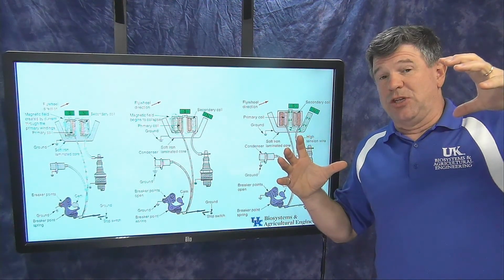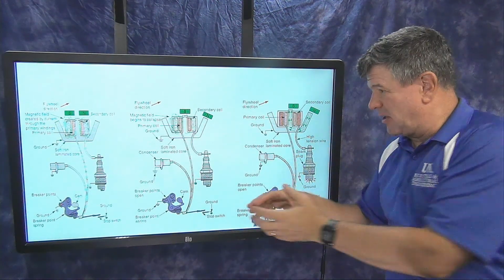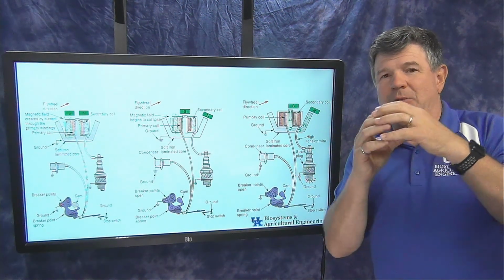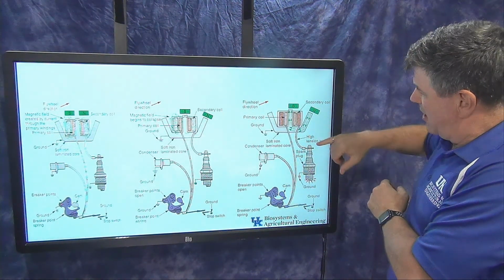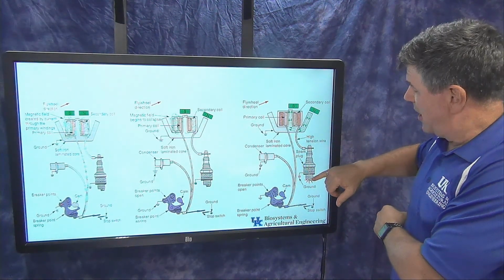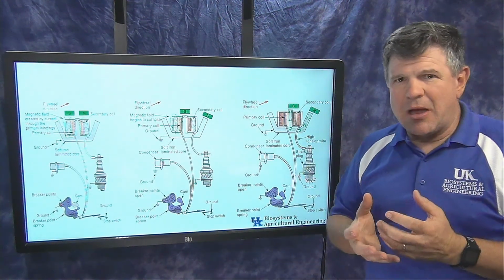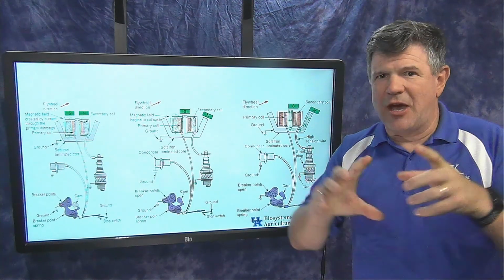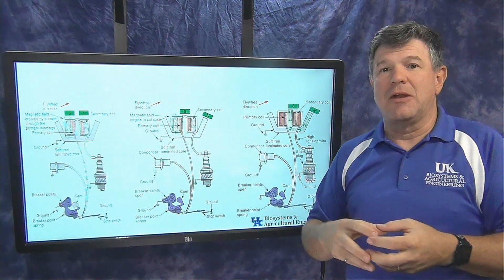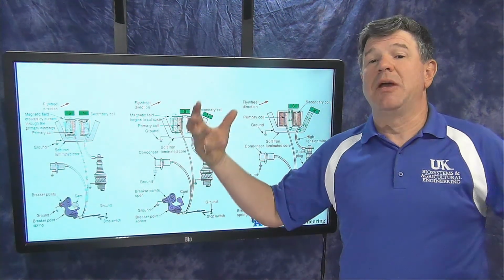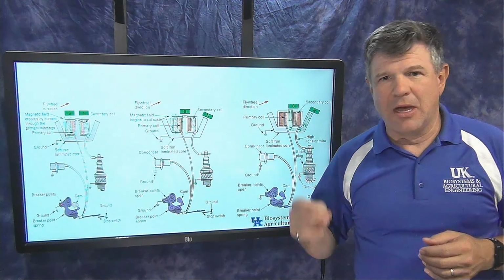So we blow up the balloon just for a real short period of time, and then it squeezes that energy back out of it. Again, it doesn't do that physically. It doesn't change size, but we can think about it like that. So we fill it up, and then it pushes it back out. And when it pushes it through that coil, there's enough energy, enough voltage, to give us that 20,000 or 30,000 volts or whatever we need down here at the spark plug to be able to jump across. Okay, so again, same kind of thing, same idea, where we've got that inductive stuff, the collapsing field or inductive kick, going across from primary to secondary coils to step up that voltage and make the voltage even bigger, and that gives us 20,000 volts, gives us a spark, and then we do it again, and we do it again, and we do it real fast.